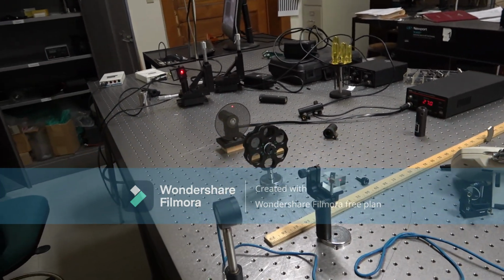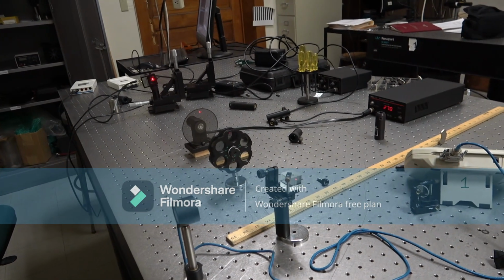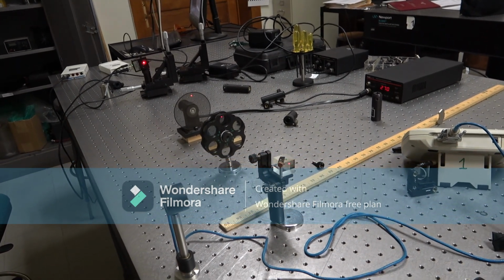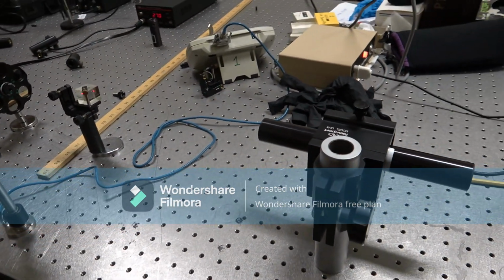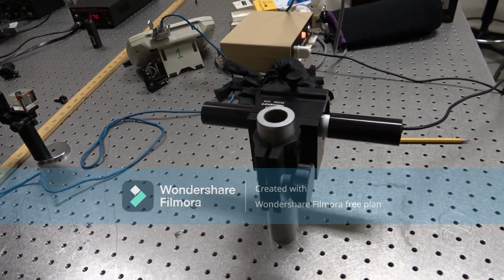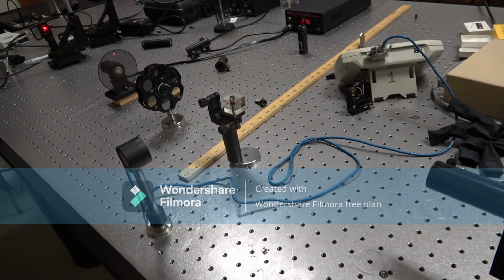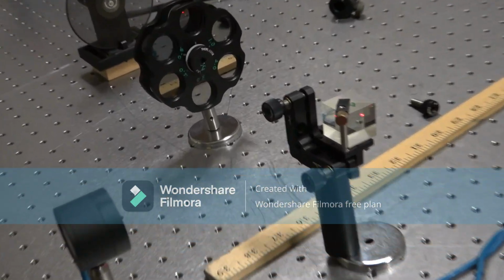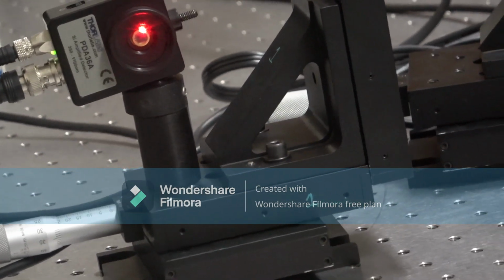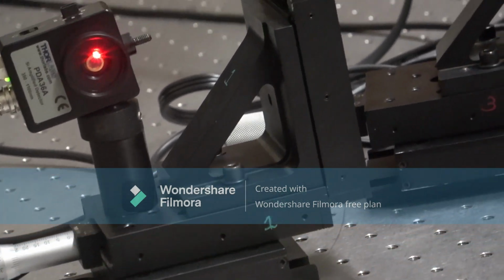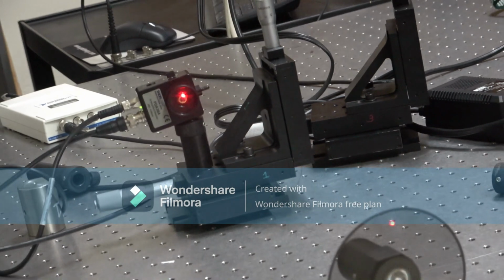The purpose of this is to ensure accurate calibration by eliminating interference from ambient light. The chopping wheel modulates the light hitting the photodiode, and the lock-in amplifier detects this specific frequency, ensuring only the desired signal from the laser is measured by the detector.